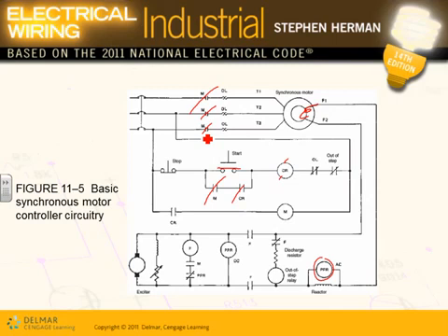The power factor will affect the branch circuits as well as the feeders. Yeah, but how does it affect the branch circuit? You're pulling more current. I'll show you an example in a second. It affects the branch. If it's a branch circuit going to a light, not a whole lot. If it's a branch circuit going to a motor and the power factor is 70, here's what happens.